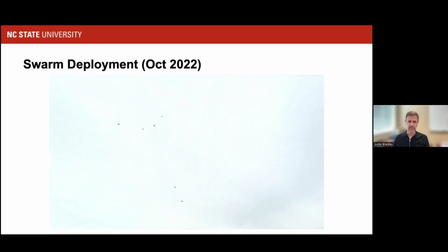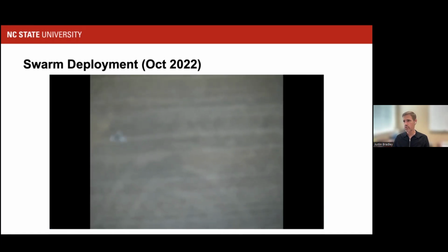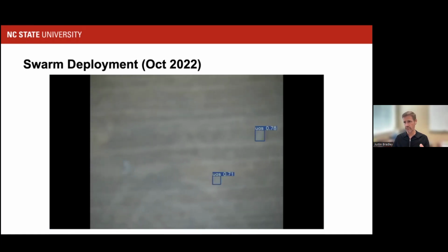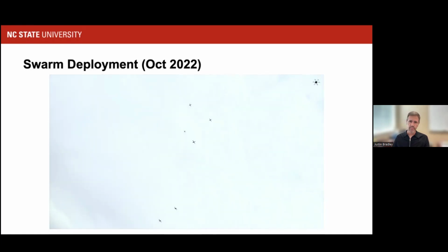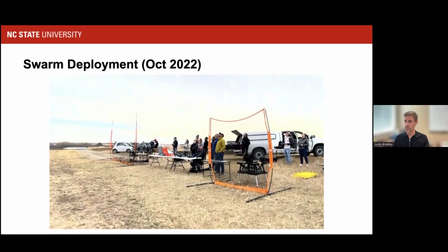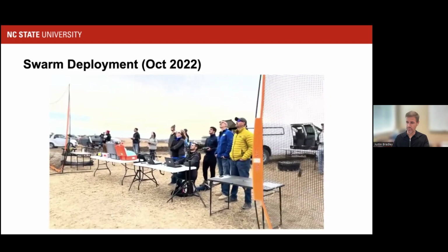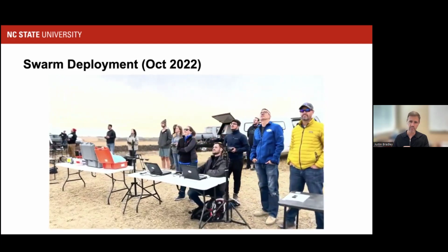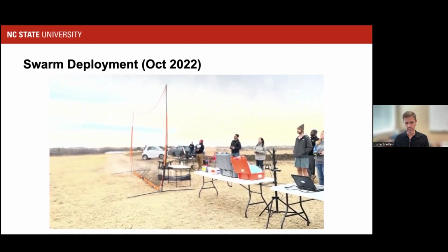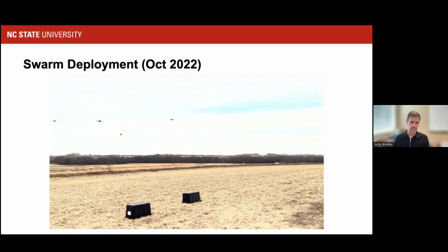So in this particular mission, after the aerial insertion, the swarm groups up and does what we just call a corkscrew loiter. So they just loiter around each other at different altitudes, making sure there's altitude separation. The larger drones have on board some machine learning-based classifiers that can identify drones moving in and out of the field of view. The more recent development on that front is that we can actually track individual drones. So we can identify not just a drone from the swarm, but which drone it is in the swarm. So that's kind of nice. It uses RGB as well as fused with infrared data.